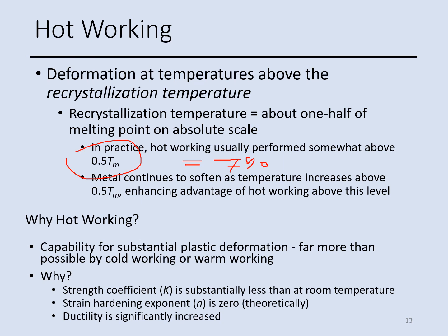So as they increase the temperature, the load for plastic deformation can be reduced, because that value K, as I mentioned before, the strength coefficient, is substantially less than the value for room temperature. And at high temperature, that n number, the exponent, becomes zero, theoretically. And ductility also increases at a hot temperature.